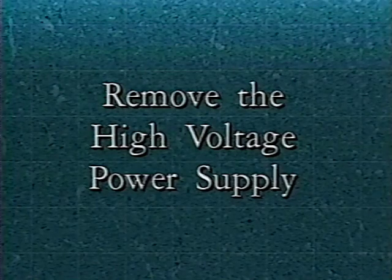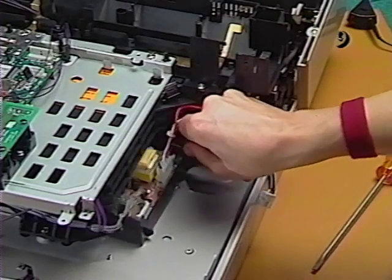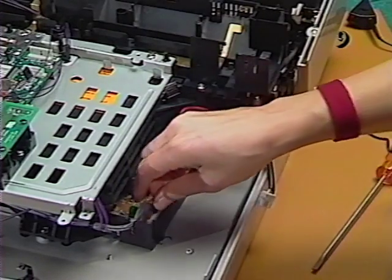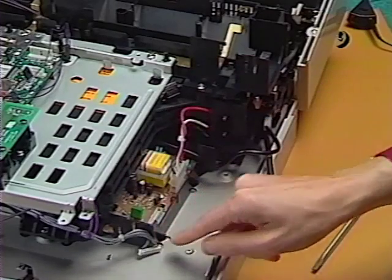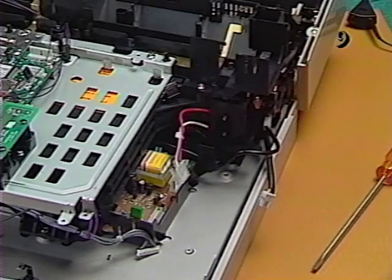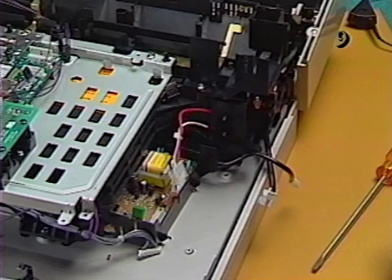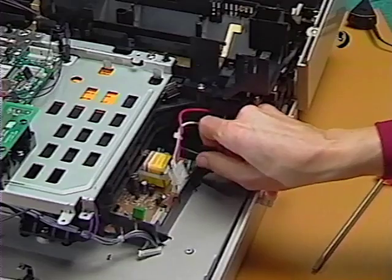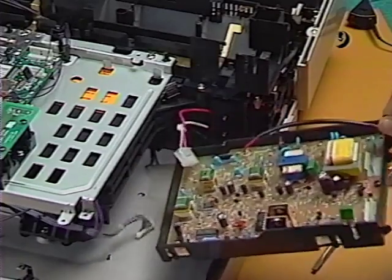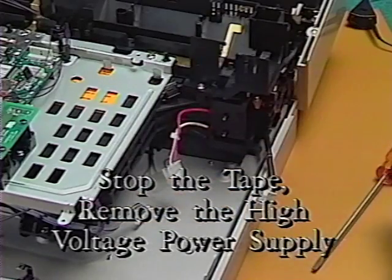Remove the high voltage power supply. First, pull the plastic tray containing the high voltage power supply out from under the scanner assembly. Disconnect connectors J601 and J602 from the high voltage power supply. Next, disconnect the black cable connecting the high voltage power supply to the high voltage contact assembly. Finally, remove the high voltage power supply from the printer. Stop the tape and remove the high voltage power supply.